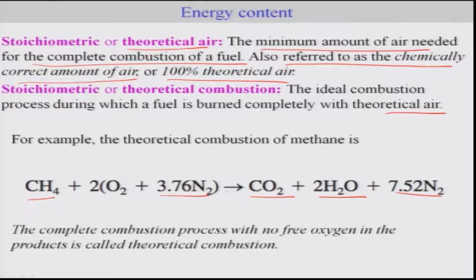Okay, so this is the complete combustion with no free oxygen in the product. And thus this is also a theoretical combustion. So that means the theoretical air here is nothing but 2 into 4.76 kilomole of air. That is something which you would call theoretical air. This becomes a kind of limit or criteria for which we can add an additional amount of air in excess, in order to have surety that the combustion will lead to completion.